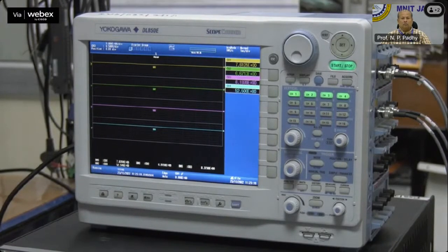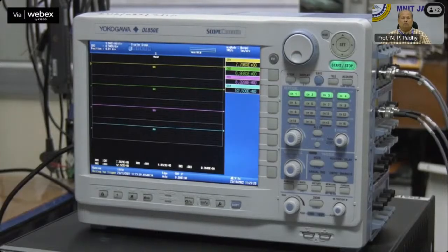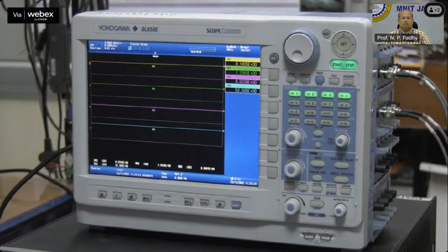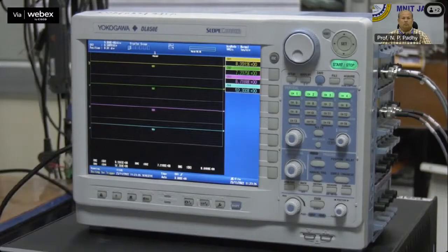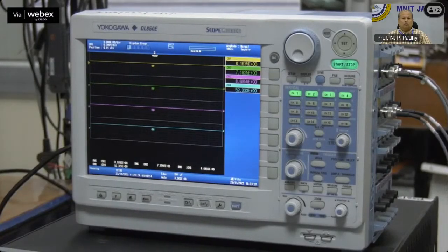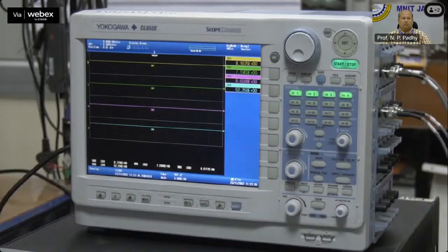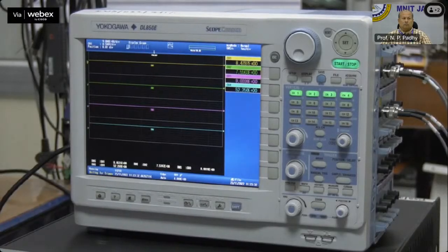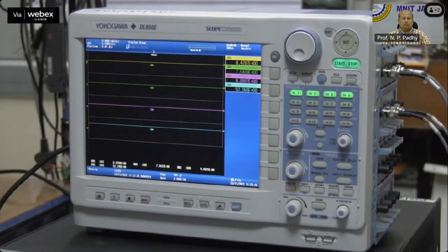We can observe the input current of batteries in the first 3 channels of the DSO. Also, the SOC values are draining faster than earlier. From this, we can understand that the algorithm handles the power demand changes without any setbacks.